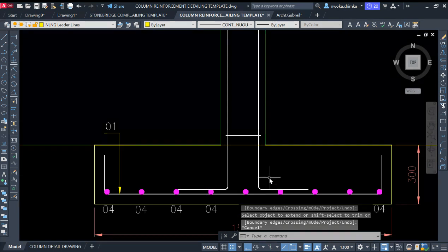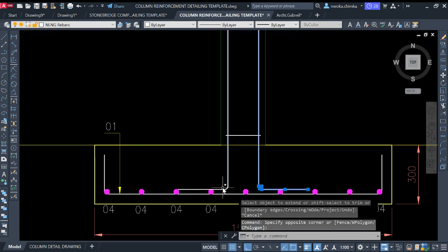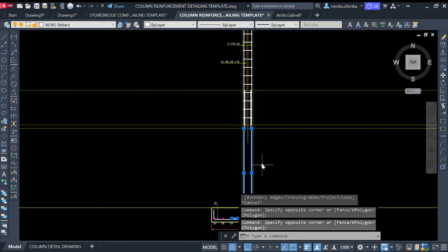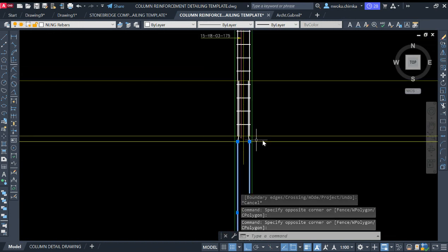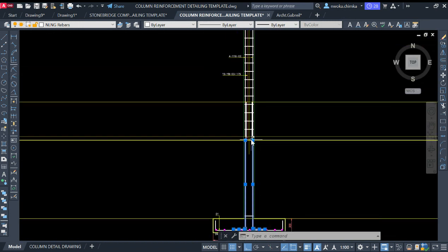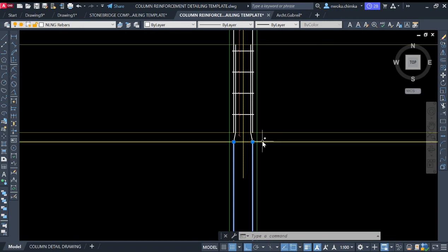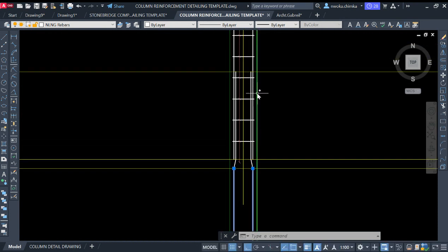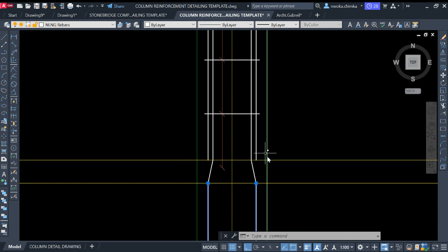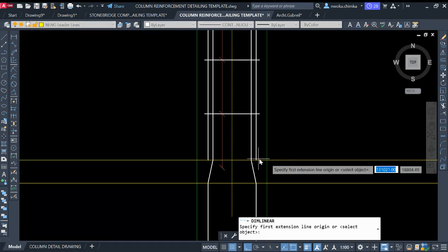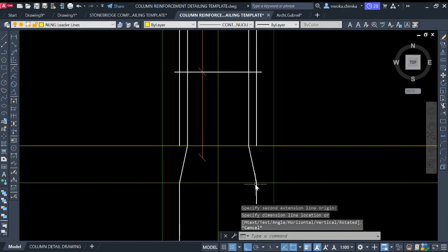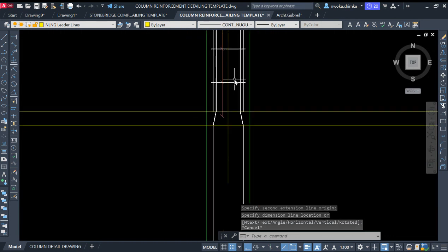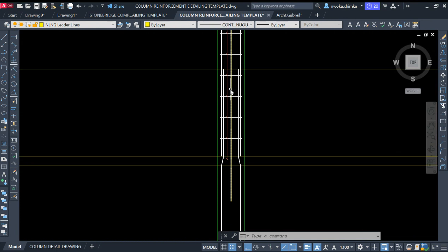So you can now see that this is the column reinforcement coming from the foundation. When it comes to this level of DPC, or let me say top of concrete, it now cuts, which now causes a lapping of 800. This is the kicker. From this kicker point of 75, it now forms a kicker, which will show a little deviation and then go upward. This is how it will be on the construction site during the construction.